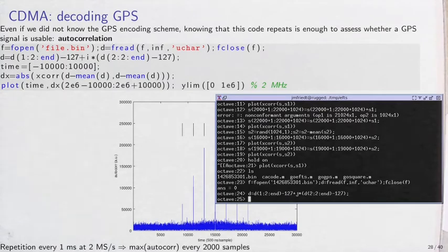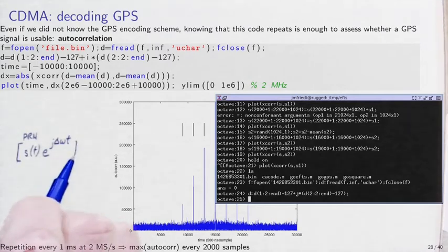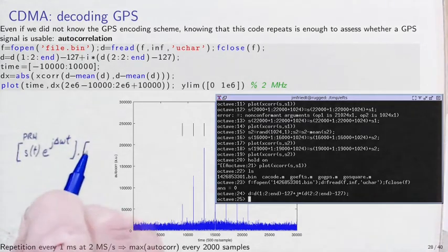So we might wonder whether there are actually signals in there, and to check this we can autocorrelate, because autocorrelation, even if there is a Doppler shift, if I have a signal with the pattern of the pseudorandom sequence of one Gold code, which is shifted by exp(j delta omega t) due to the frequency offset, the correlation will multiply with the complex conjugate of this term.